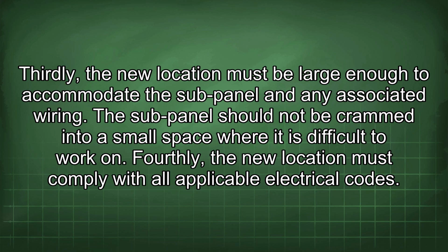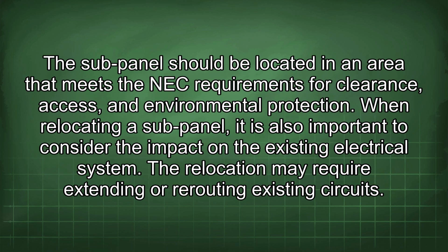Thirdly, the new location must be large enough to accommodate the sub-panel and any associated wiring. The sub-panel should not be crammed into a small space where it is difficult to work on. Fourthly, the new location must comply with all applicable electrical codes. The sub-panel should be located in an area that meets the NEC requirements for clearance, access, and environmental protection.